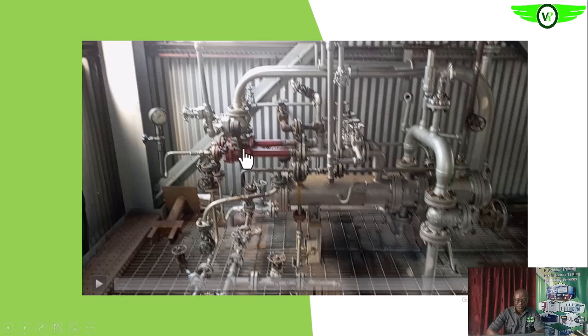So you see the two ejectors. Once steam is administered into this ejector system, what happens? As it's working, it pulls vacuum, or pulls whatever is on the line to your exhaust system, through into this condenser again, which is a heat exchanger.